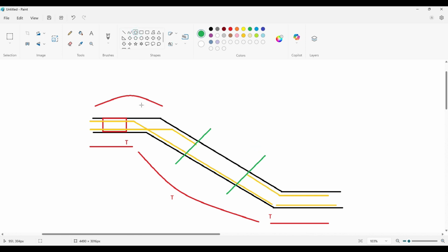Now one more thing to keep in mind is about the distribution bars. So distribution bars will be something like this. Okay, the main bar is there, and on top of the main bar all the distribution bars will be present like this. And when these distribution bars come over here, they will come and support the main bar from underneath, just the way it used to happen for the slabs, right? Same thing happens over here. So if you see here, distribution bars will come on the inner side. Whatever is seen in yellow are main bars, and whatever is seen in green are distribution bars.